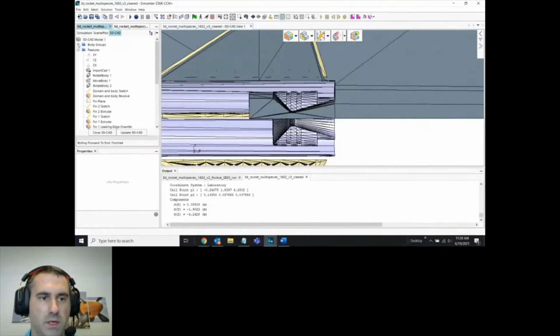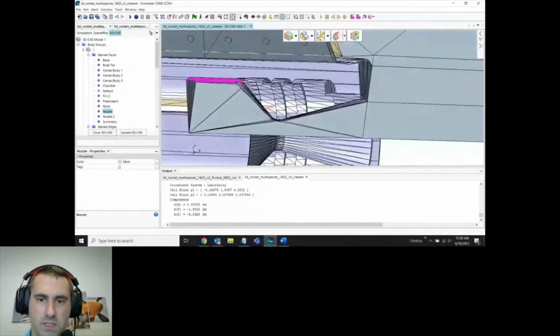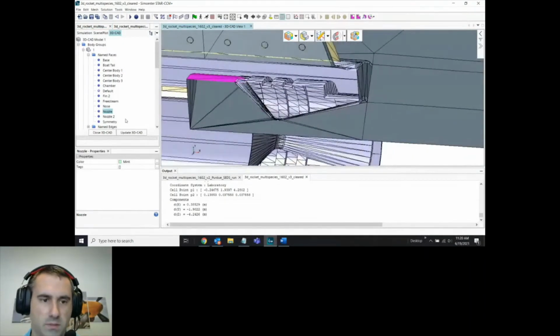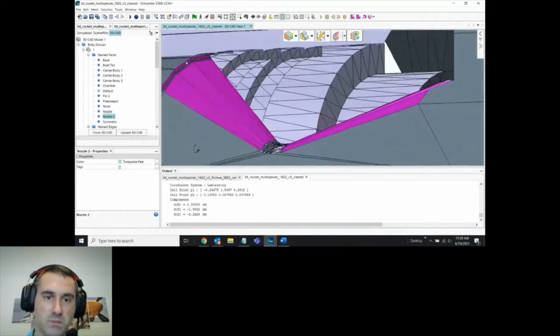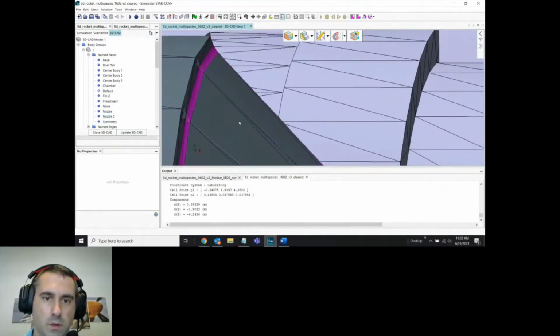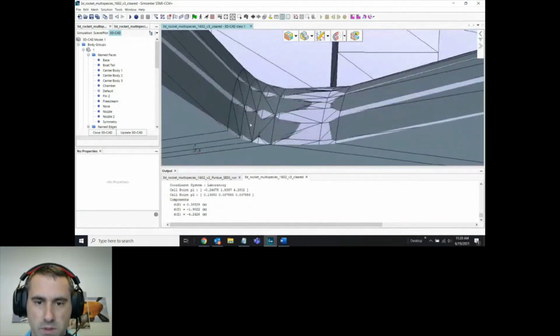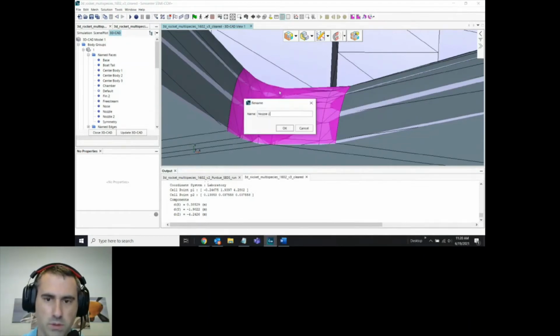Now, the reason why I was saying I don't want you to delete too many surfaces is because what you'll notice here is that nozzle is now just this CAD, right? It used to be all of this, but now not so much. Well, between nozzle and nozzle 2, that is. So what I'll need to do is make sure that this geometry in here is actually associated to the surface it's supposed to be connected to. So what I can do is click this, and I think it was this one, and I can right click this, rename nozzle 2. So this will get dropped into this surface.